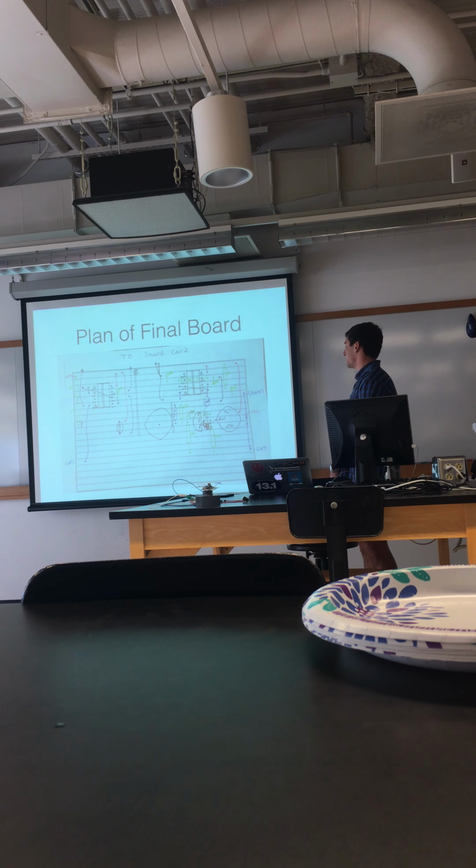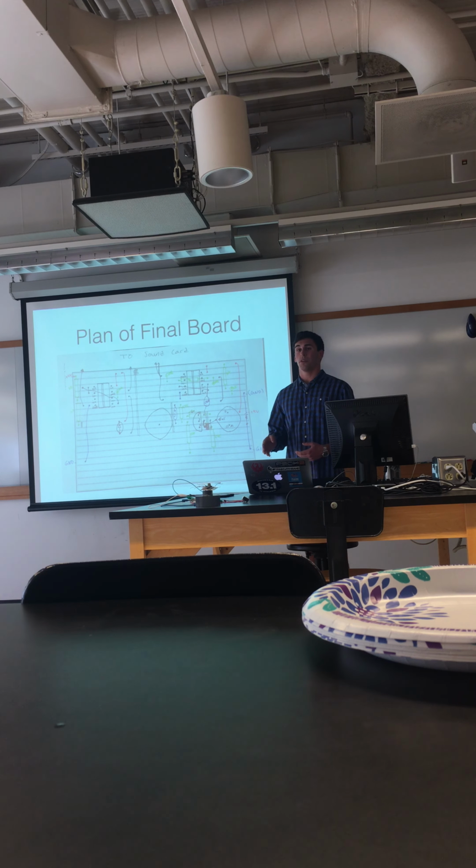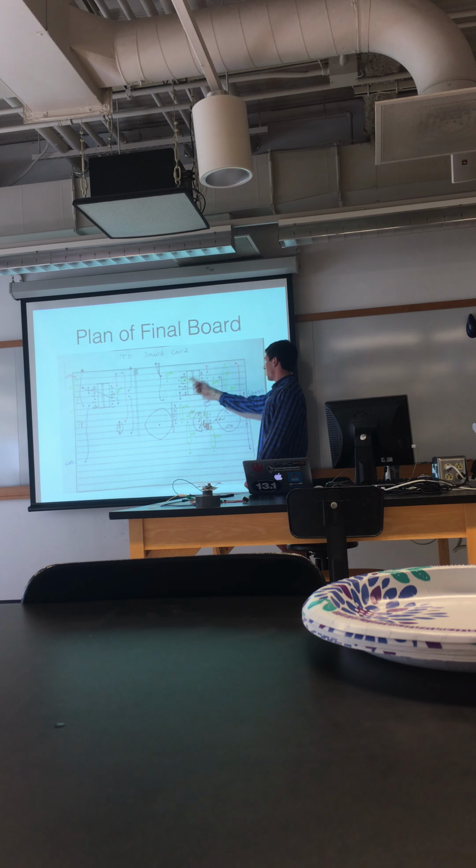And the reason that I had to do this and plan it out and figure out exactly where each component was going to be going was because this board doesn't have a specific power or ground strip, right? So it's not like a regular breadboard. I can make any strip whatever I want it to be. And these strips all run horizontally across the entire board.